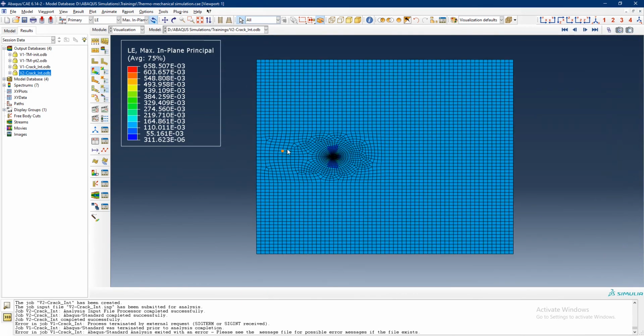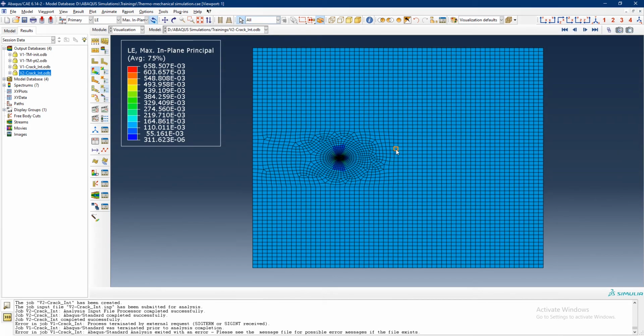And in the future I want to make a simulation where I apply a cyclic load or cyclic displacement here, and you can see that the crack faces open up when a tensile load is defined, and the crack faces close together and basically join together to form a contact when there is a compressive cycle. This is an interesting thing to learn and apply in our simulations when there is a crack and the model is under compressive loads or compressive stresses, because then this can give a better approximation of results.